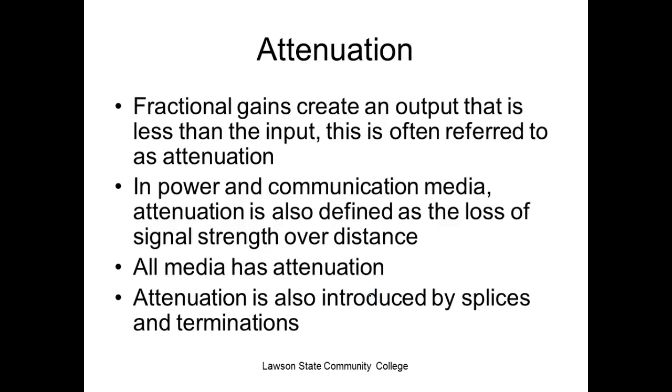Are we okay? Fractional gains create an output that is less than the input. This is often referred to as an attenuation. In power and communication media, attenuation is also defined as the loss of signal strength over distance. All media has attenuation. Attenuation is also introduced by splices and terminations, which is what we're going to learn here, right? So our goal is to not add any attenuation at all when we do our splices.